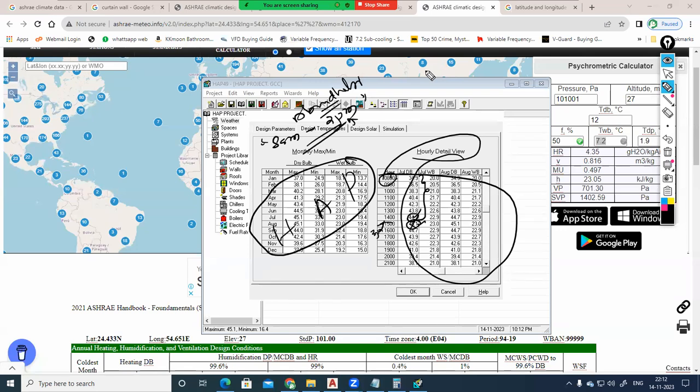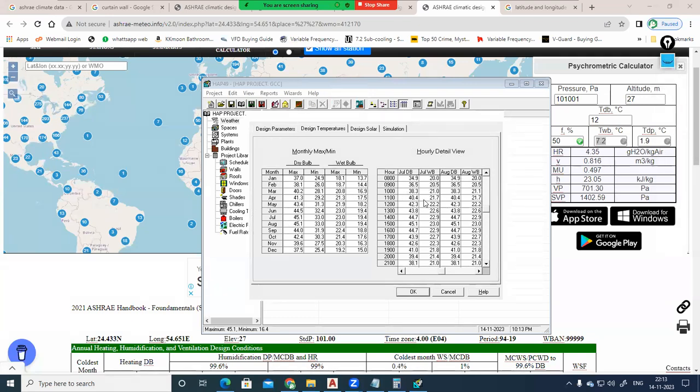Okay. In Revit and others, we have this heating and cooling load calculation analysis option, but the output that we are getting from Revit is not proper. So when we are doing the calculations in Revit, all the spaces we will be converting into a format called GBXML, Green Building XML. Then we will be uploading into third-party analysis software like HAP, Trace 700, different software is there. Then we can analyze. Comparing to all the other software, HAP is good. It has good accuracy. Okay. Fine. Anyhow, these temperatures are editable. If the client is asking to edit the temperature in this, you can.